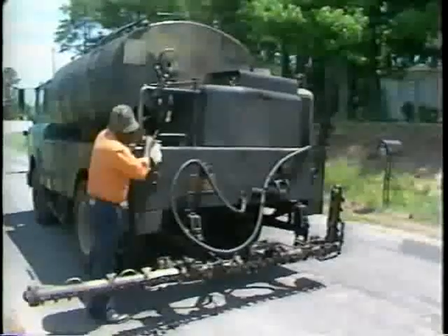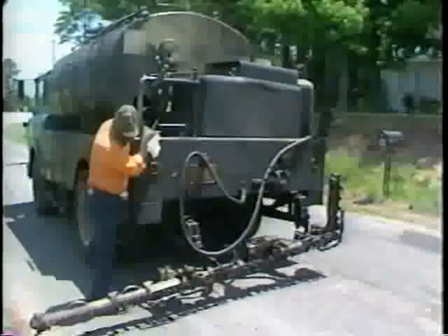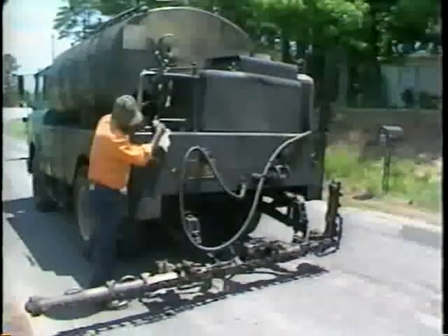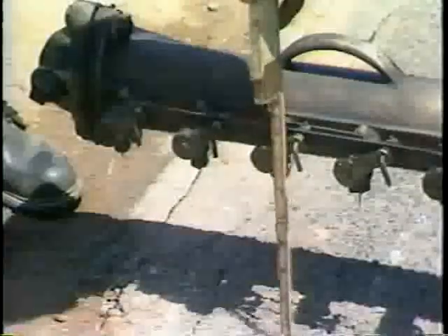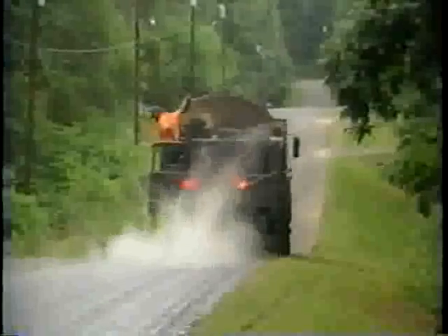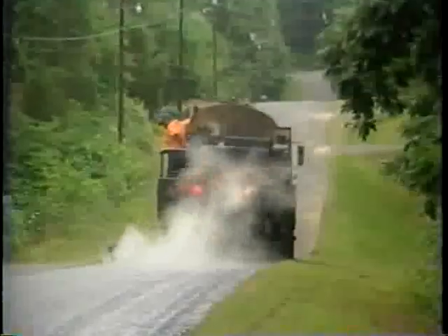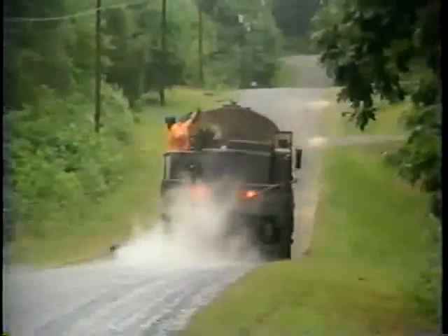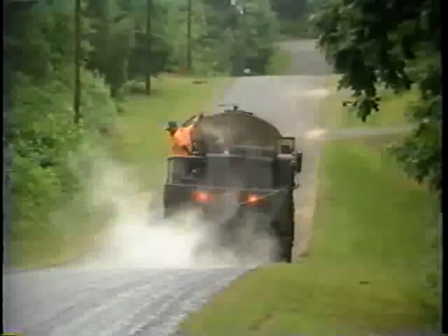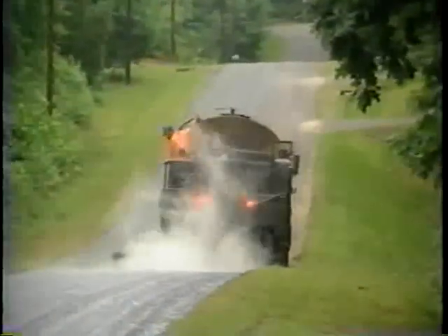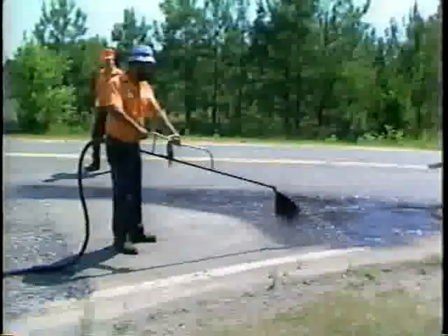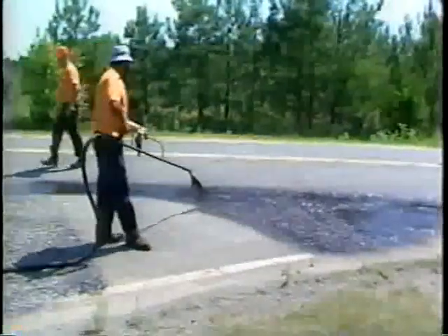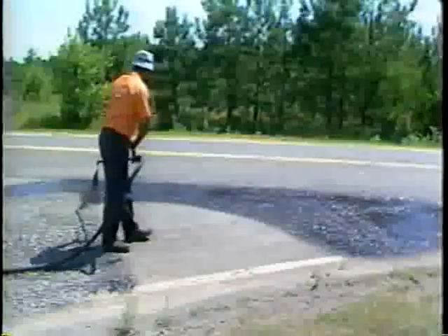Follow the manufacturer's instructions for specific distributors for adjusting spray bar height and nozzle settings, so that the desired application rate and coverage is achieved. The distributor uniformly applies asphalt to a surface at a specified rate, regardless of changes in grade or direction of movement. A hand spray attachment is convenient for applying asphalt in areas that are hard to reach with the spray bar.